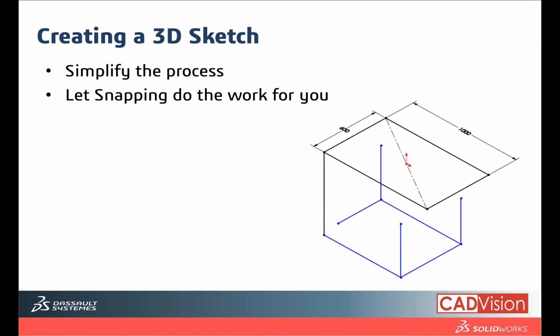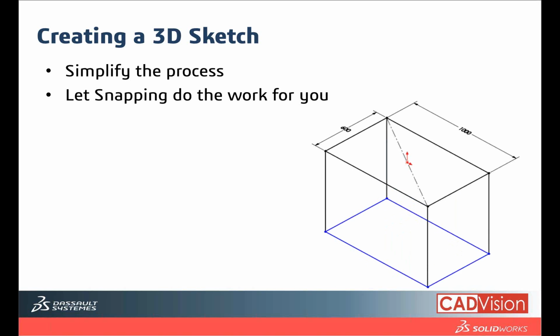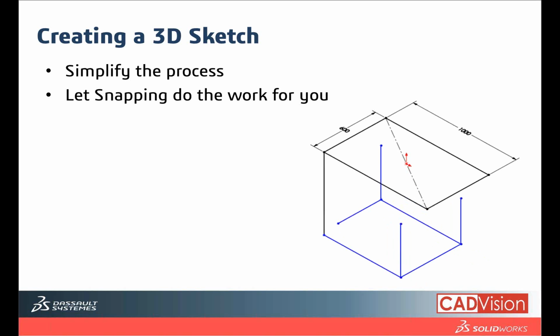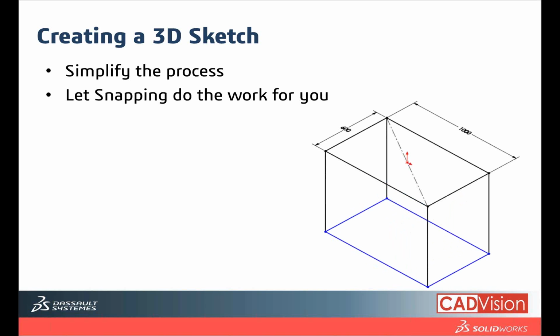All you need to do is draw a basic frame, just like you do in the 2D sketch. Then click on two points and join them by adding a coincident relation, or you simply drag each point and snap it to the point that you want.